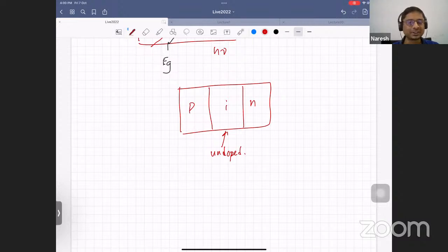What we did was simply a phenomenological model where we said we have capacitors in series, and so on. But if you actually do this at different frequencies, we don't just do one HFCV and one LFCV. LFCV is in fact very difficult to do. What we do is make a CV measurement at 1 megahertz, 100 kilohertz, 10 kilohertz, 5 kilohertz, and so on.